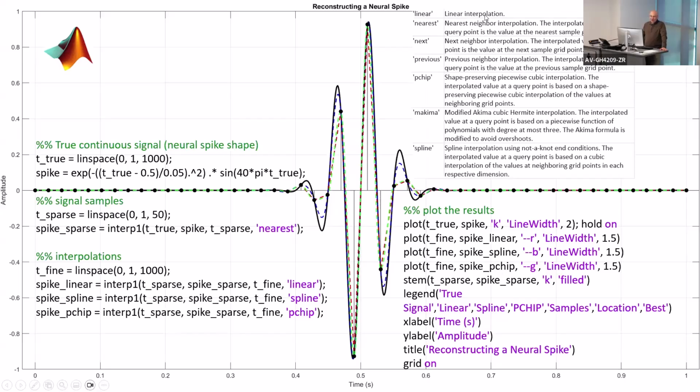And these are different kinds of interpolations that you have in that function in MATLAB. You have nearest, previous, pchip, Makima, spline, all kinds, okay? Each one of them has particular advantages or disadvantages. You can read about when you want to use them and how you want to use them, but in terms of using that in MATLAB, it's just switching that word. Instead of pchip, you can put here Makima, it will give you something else. Other types of interpolation. So some of them are more computationally expensive, some less computationally expensive, but this is the idea.